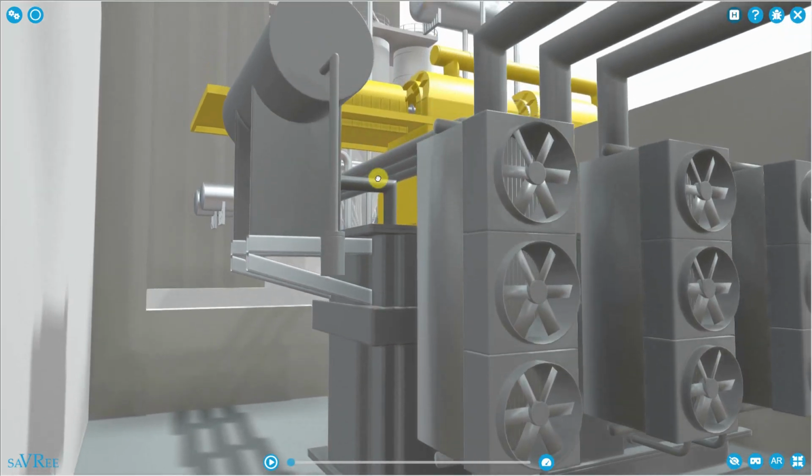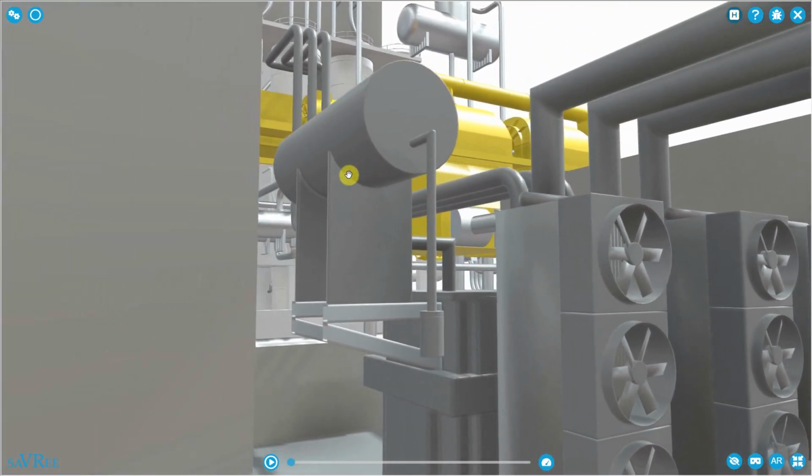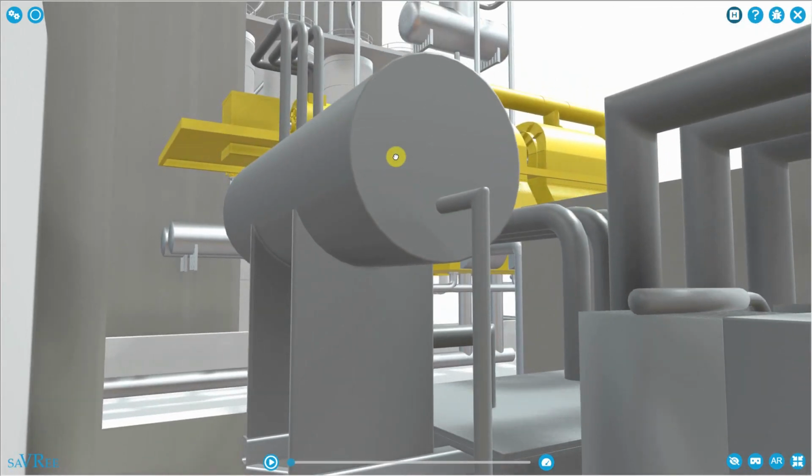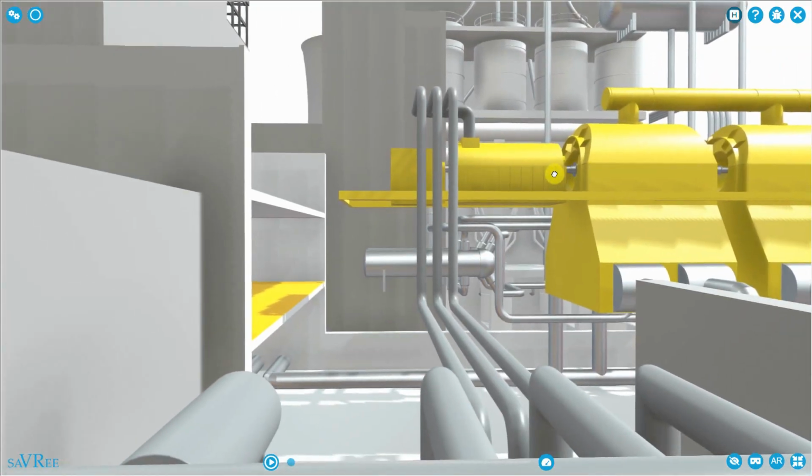We call it a conservator type transformer because we have this conservator tank up here. It's an expansion tank, similar to that which you'd have on a combustion engine if you're looking at the cooling water system, also known as the jacket water system.